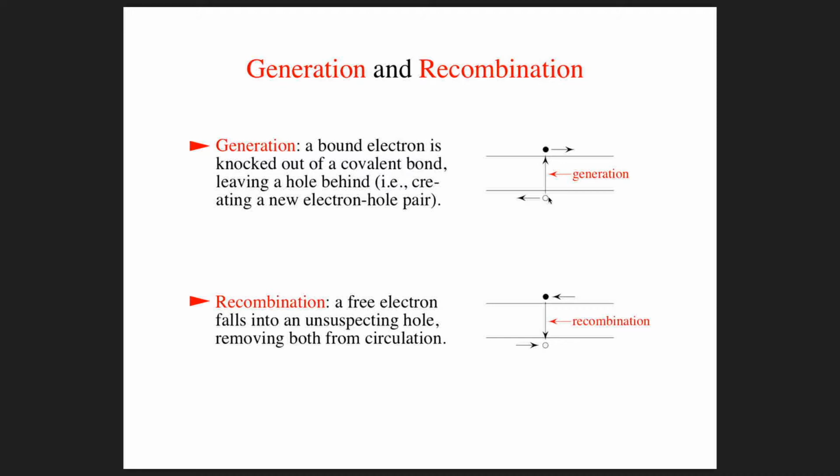For instance, you can have light photons incident onto a chunk of silicon, and visible light actually has enough energy to do this. And so this is actually how photodiodes and phototransistors work. This is how the pixels in your camera on your cell phone actually turn the photons that are coming in a given region into an electrical signal. So what happens is a photon comes in here and liberates one of these electrons in the valence band into the conduction band, and that generates an electron-hole pair, and then the number of electrons generated this way might be collected for a certain shutter period of time, and then you read out the number of electrons